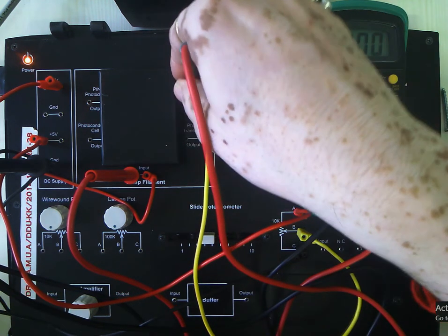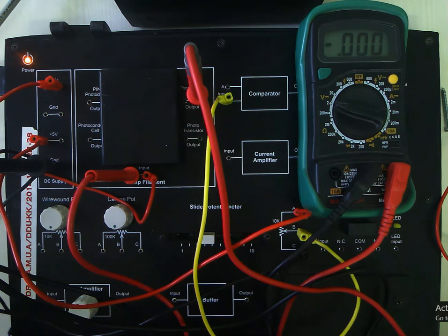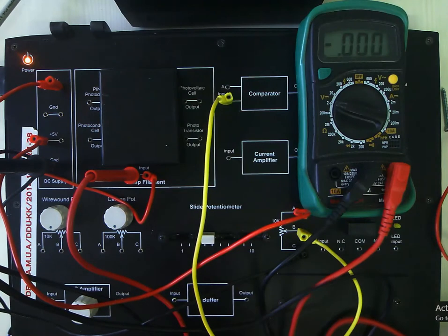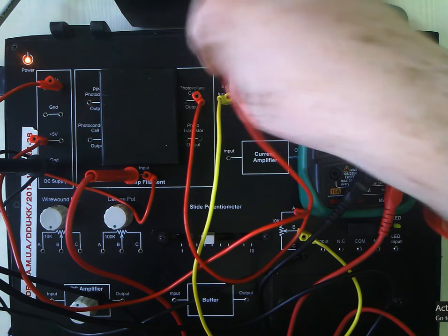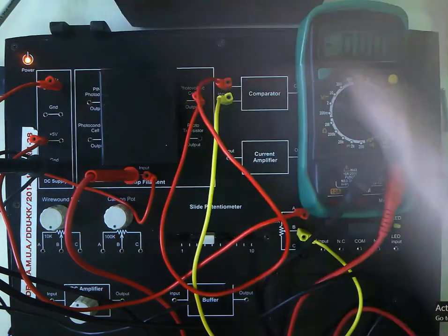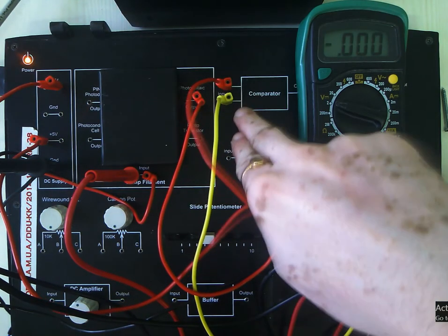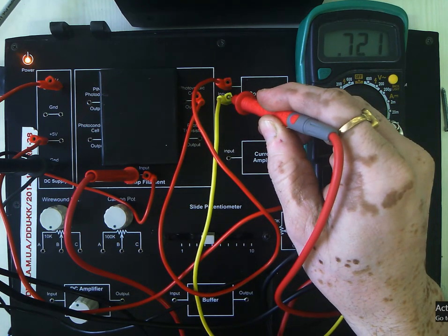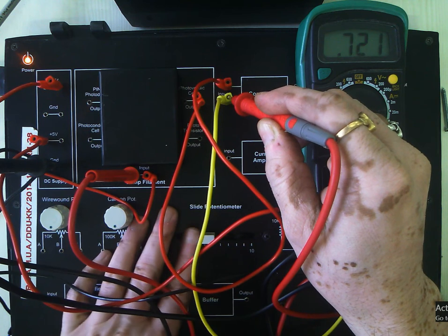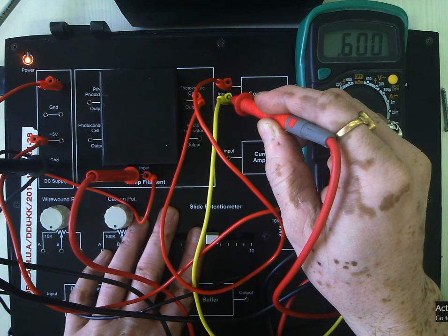Now we will see the span of the operation of this photovoltaic cell once again. You can find it can go well below and above that 0.7. Now you can see I will be applying the output of the photovoltaic cell to the test terminal of the comparator. So now you see here the condition. What is the voltage at this yellow pin? You can see it is the reference terminal. We have got, I will make it lesser, 0.5 I will make.